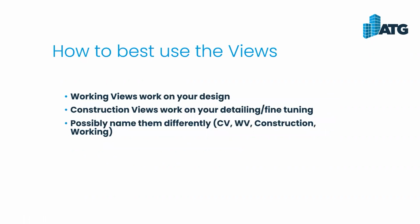All right, so how to best use your views. I kind of harped on this a little bit here. Working views, obviously, work on your design aspect. Construction views, work on your detailing, your fine tuning of your view. If you're adding any type of line work items, you want to make sure that you're adding those into your construction views. Those, again, will not carry over into your working views.